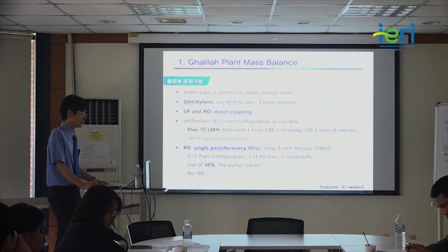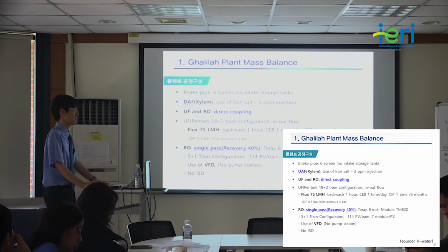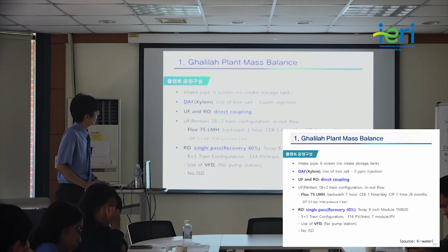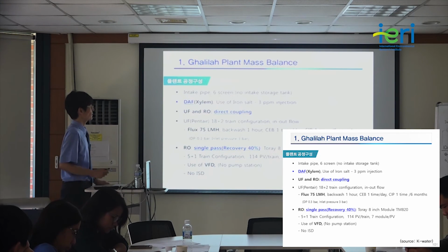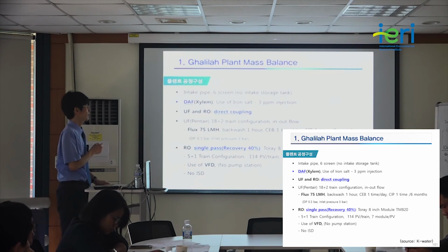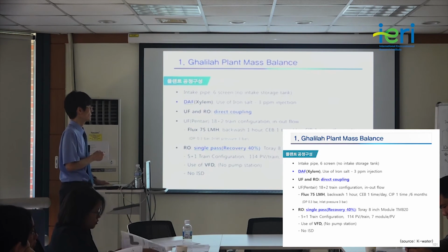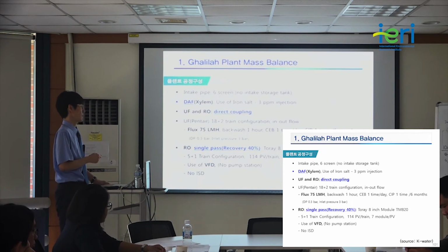So other operating and design factors were considered and investigated. In fact, after the analysis, it was found that they have this intake pipe and screens and dissolved air flotation with chemical addition and ultrafiltration membranes, flux of 75 LMH, with these conditions, which are not really special.